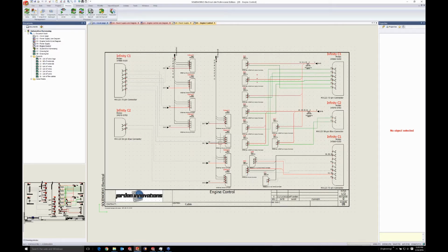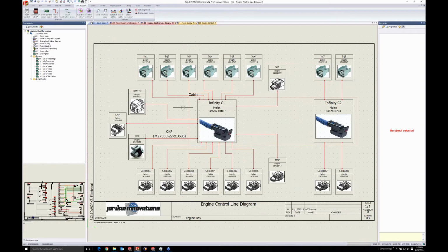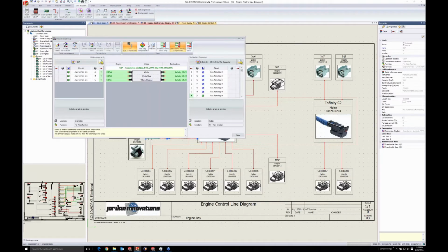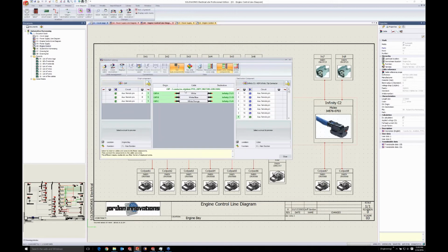As far as the background, as far as what we need to route, we can do it with something like this, a single line document. We can go in here and define a cable. This is my crank angle sensor. It's a Hall effect sensor, not necessarily high speed. Gas turbine guys are reading hundreds of thousands of RPM; we're reading a couple thousand RPM. But this is really what helps the engine computer determine all of the subsequent events, so we really need an accurate signal here.